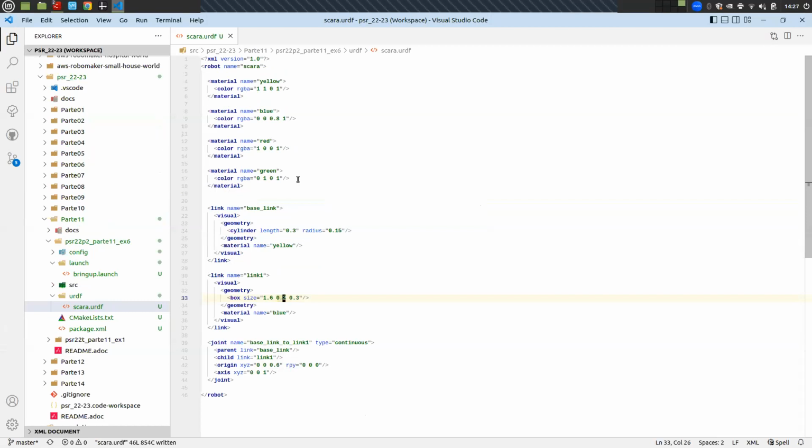We change it here. So when we put the geometry, we can also tell, so whenever you draw a box, the coordinate system of the box is the center of the box. And you didn't want the center to be the coordinate system, we wanted the bottom of the box. So you have to subtract half its length. I'm in the wrong place. It's here in the box. So this is the origin.